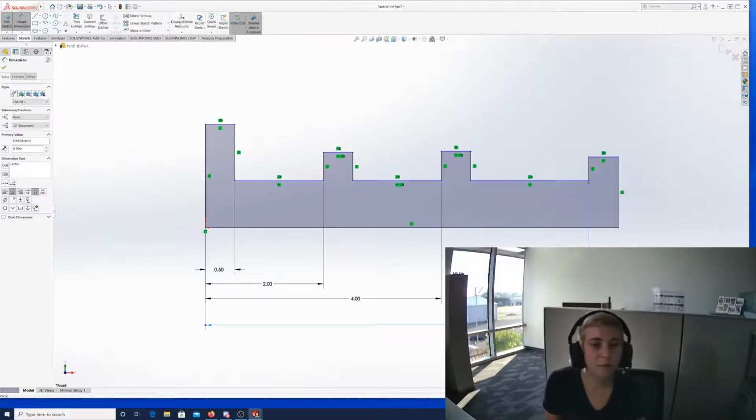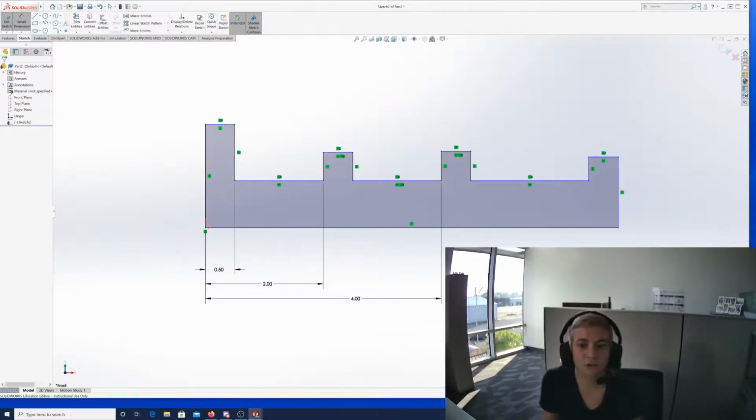Okay. It's probably because your sketch was pretty small to begin with. So when you start adding dimensions, a lot of the time you're going to end up with things changing shape in really weird ways. Because say everything in your drawing all fits into 1 meter, and then you say, well, I want everything bigger. I'm going to add a dimension here that says it's 2 meters. All of a sudden, that's going to be the biggest part of your drawing because everything else is still tiny. So it should be fine. You'll just need to zoom out to where you can see everything.